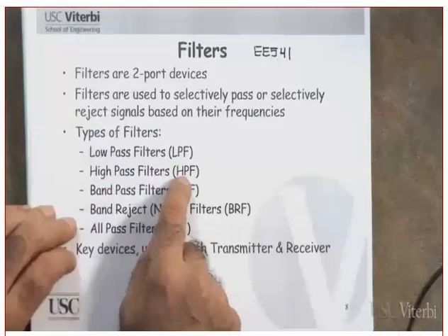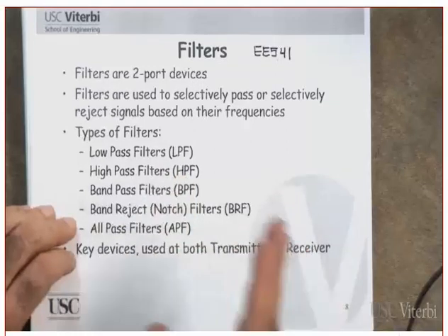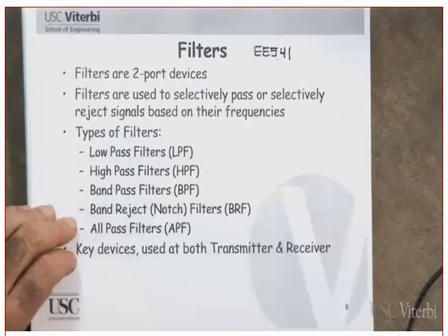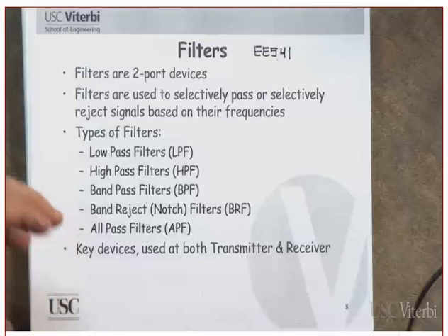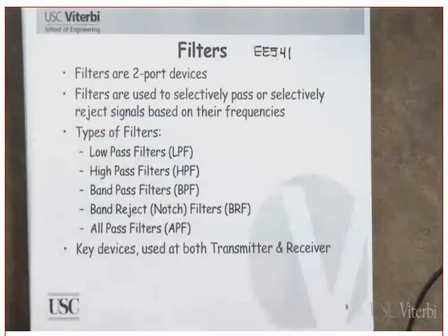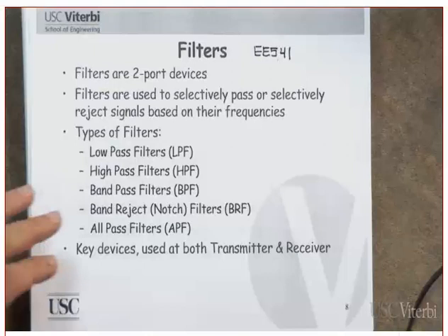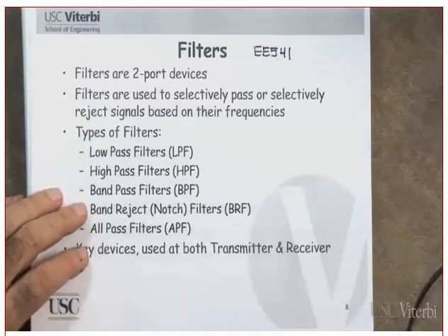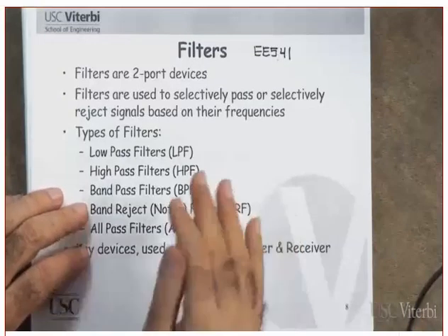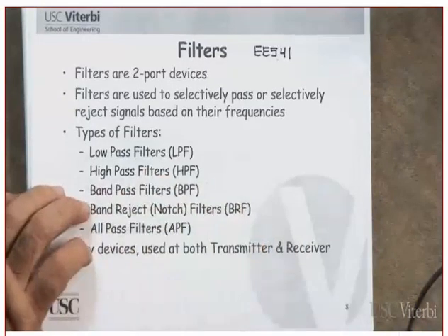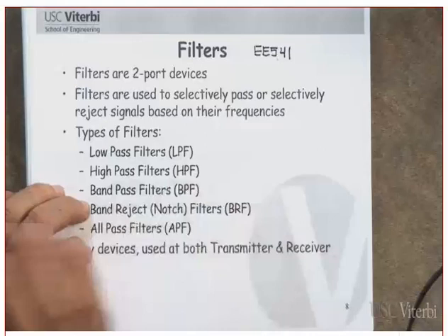These are not desirable. Why? High pass filters are not desirable. Remember what I told you. A high pass filter passes high frequency components. Why are they not desirable? Noise occupies the entire spectrum. If you are passing high frequency components, a large percentage of the noise will go through the filter. Clear? It's better always to use a low pass filter instead of the high pass.